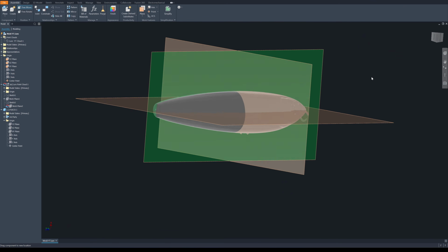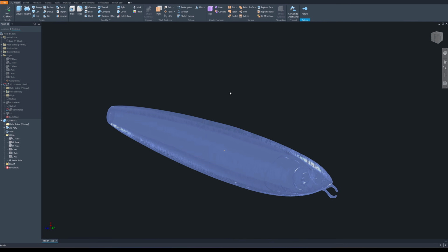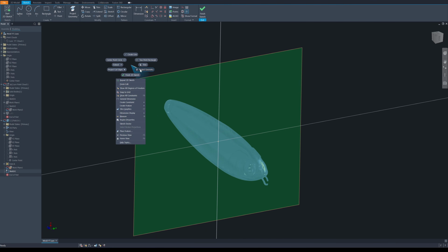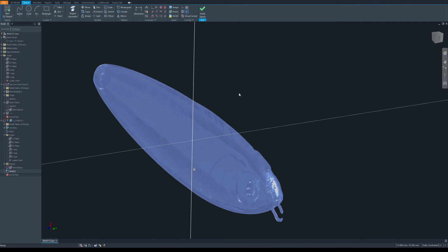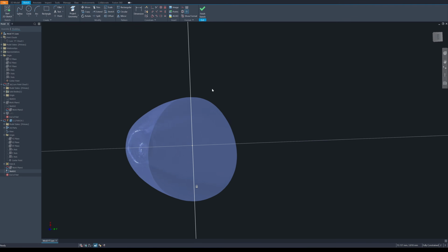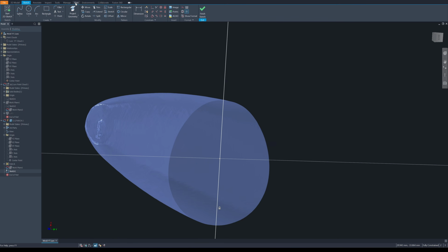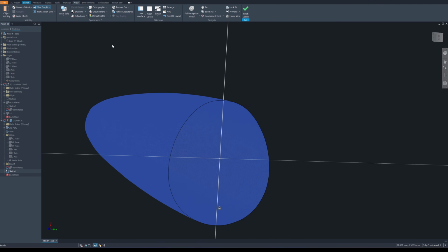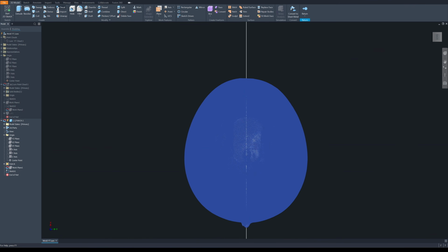Because there is no flat plane. If there is a flat plane, you can build a plane inside the mesh and align it to the XY plane. I will click on creating a sketch on the XY plane, and then I'm going to project the X-axis. Next, I'm going to hit F7 on my keyboard. It's going to slice the plane, but you don't see any line that you can trace. You need to go to the view, shade with edges. The line is in black color. You need to change the color.